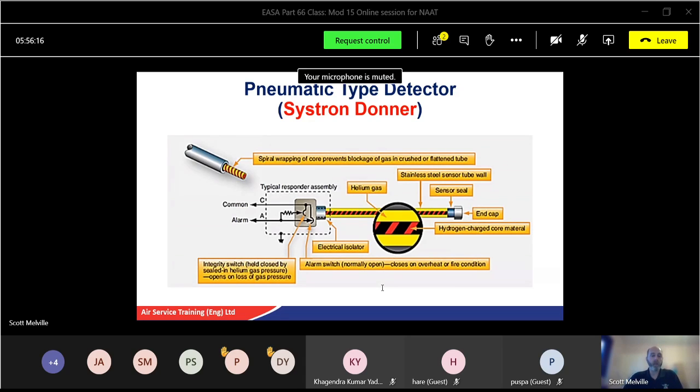Integrity of the element, you want to check it, and the system circuitry is continuously checked using what is called an automatic fault monitor control module, or an AFMCM. Okay, again, I wouldn't worry too much about that one. Just be aware, we won't go through these ones. Be aware of the different types of detectors: point detectors, the firewire, the names of them, and that sort of thing.